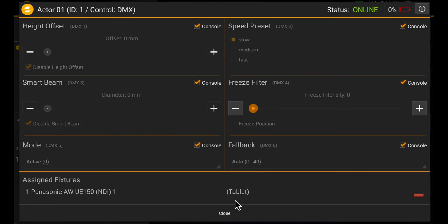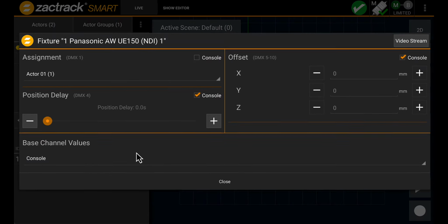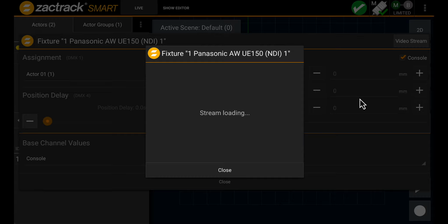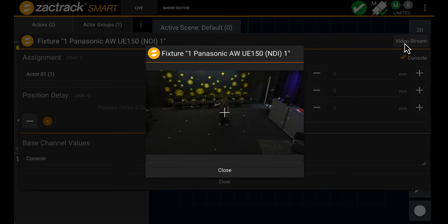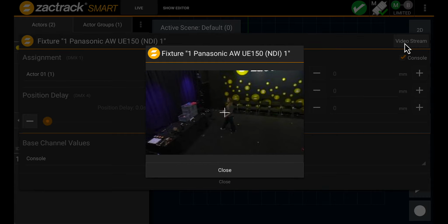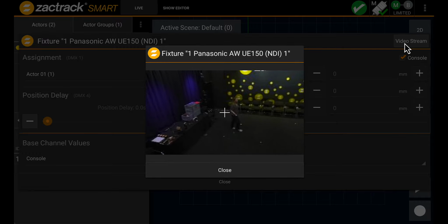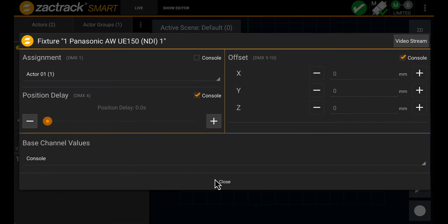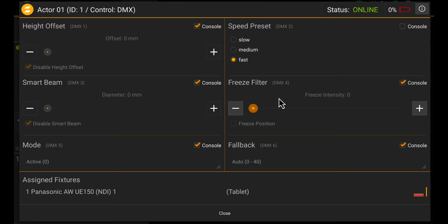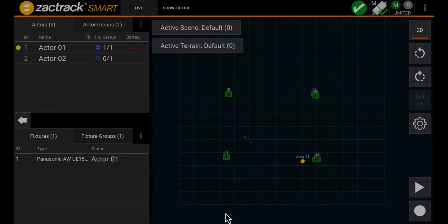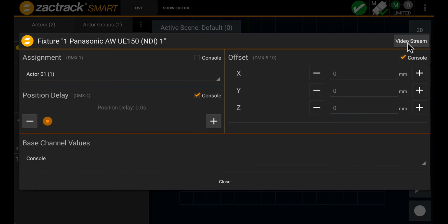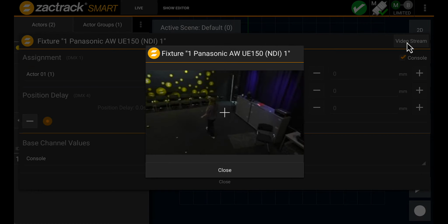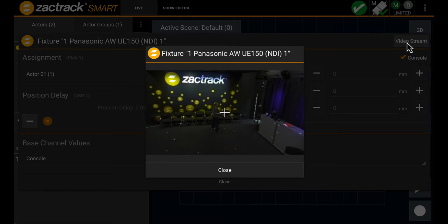When using relative control, overshoot is normal if the tracker moves quickly and stops suddenly. The camera might swing a little past the target before settling. That's expected. It's a result of how directional movement is processed, and it's often more natural looking than a hard stop. And finally, if you notice jerky movement or a slow response on an absolute camera, that's likely buffering. Some cameras can't handle the rapid position updates, which is exactly why relative control is so helpful. It lowers the data load and keeps the movement smooth, even when the tracking is fast and unpredictable.